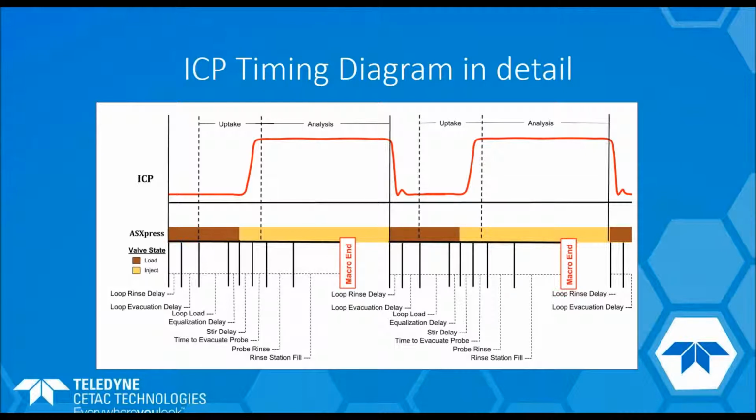Because the carrier solution, if you notice, there were bubbles, there were white spots kind of going through there. We introduced air bubbles into the carrier flow. What that does is it provides a barrier between your rinse solution and your sample solution so that they can't bleed together and drag out over time. It also provides this alternating surface tension, which really helps drive the contaminants out.